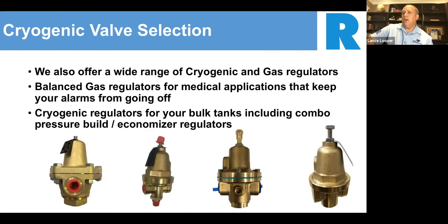What does that do for you? I tell you this, I've seen many regulators at medical facilities, and if there's a pressure fluctuation and the downstream pressure fluctuates too much, some of your alarms will go off, and that's what causes your service techs to have to go out and dismantle some of those alarms. So it's a great regulator to use, and I've been using them on manifolds for a long time. If you ever want to do an upgrade, we have them in stock, and I'll work you through how to do that.